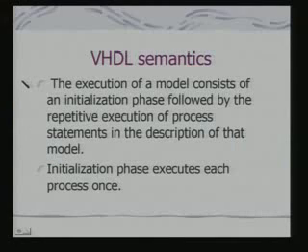What are the semantics? Once you have specified the model, the semantics tells you how it will actually be simulated. Execution of a model consists of an initialization phase followed by the repetitive execution of process statements in the description of that model. An initialization phase executes each process once.